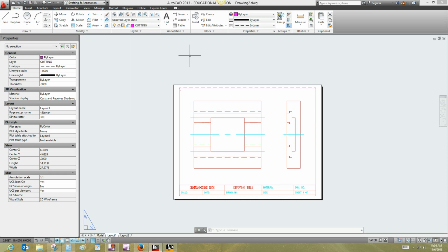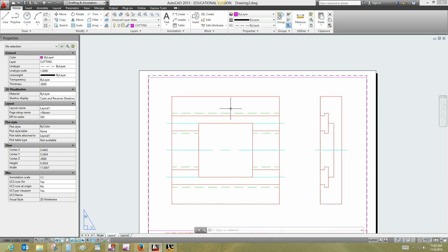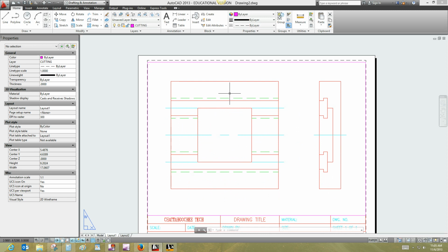Now, I'm actually looking at page 250 in your Technical Drawing with Engineering Graphics text by Gasecki, and it actually defines the size of the arrowhead there, but I've already worked out this math, and so the length of our arrowhead should be 0.175, and the broadest part of the arrowhead should have a width of 0.1.